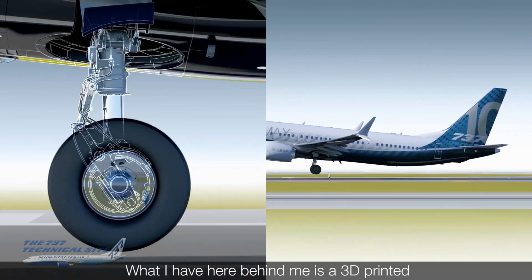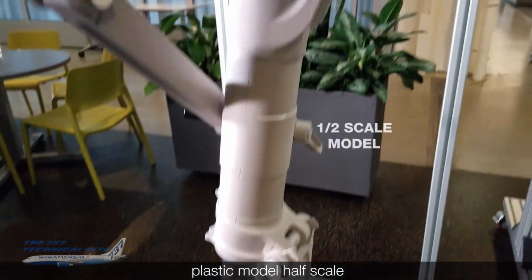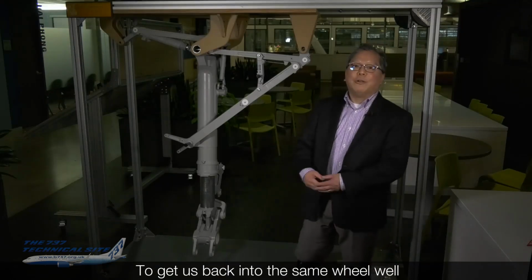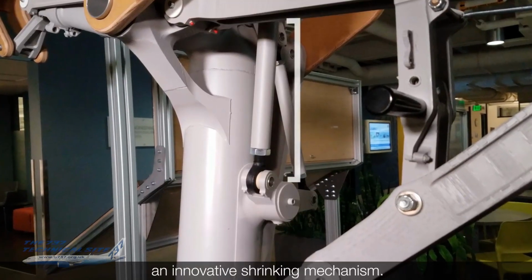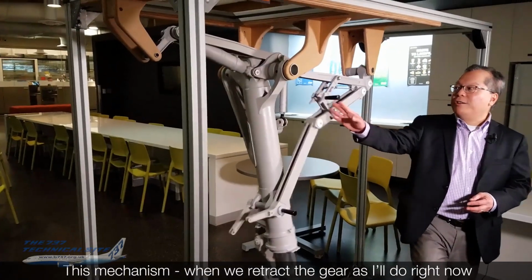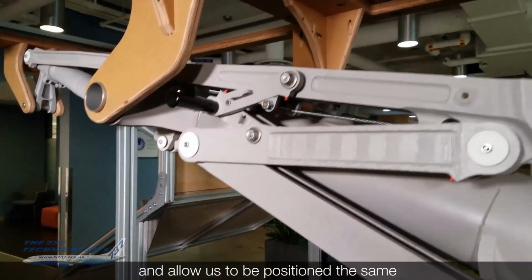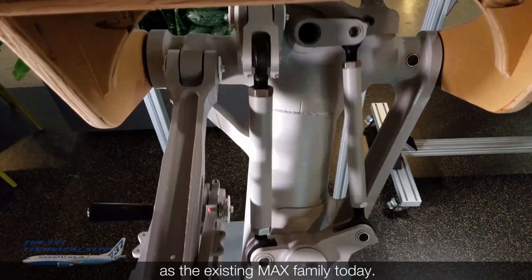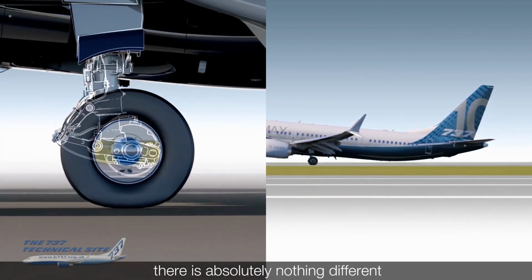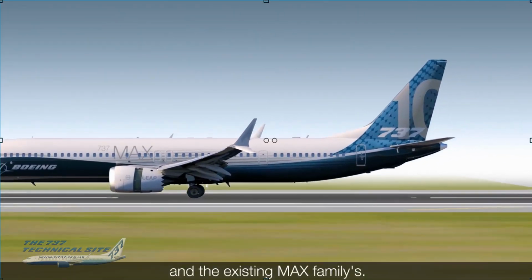Now what I have here behind me is a 3D printed plastic model, half scale, that represents the complete design functionality. Now to get us back into the same wheel well, the engineering team has come up with an innovative shrinking mechanism. And this mechanism, when we retract the gear, as I'll do right now, will pull up the inner cylinder and allow us to be positioned the same as the existing Max family today. From a pilot's perspective, there's absolutely nothing different between the Max 10 main landing gear and the existing Max families.